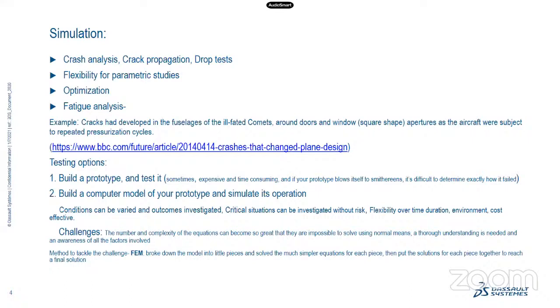What is the cyclic load about in an aircraft? We have pressure during takeoff, then during flight, and then again landing, again takeoff. So this is one cycle. The prediction was something like a 10,000-cycle life, but before that it crashed. Maybe after 1,000 cycles, it crashed because of this stress concentration and durability, cyclic loading.